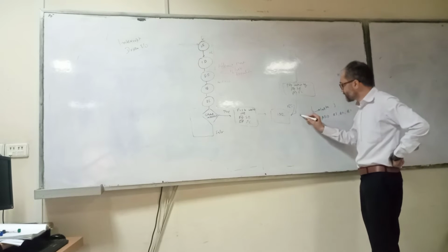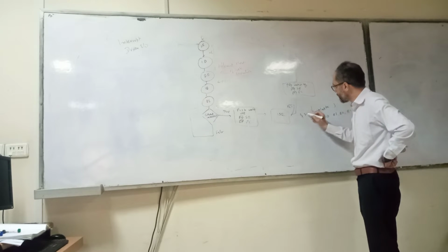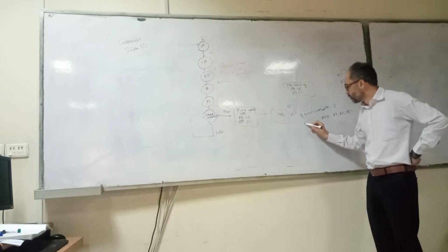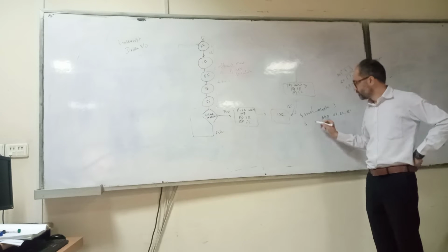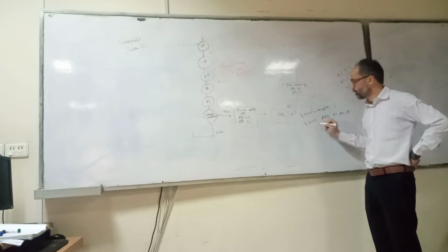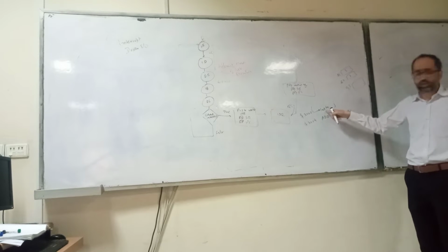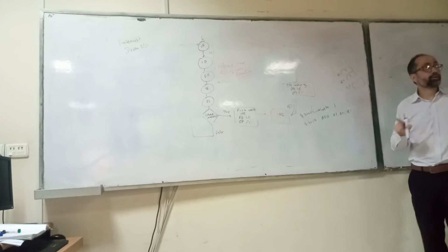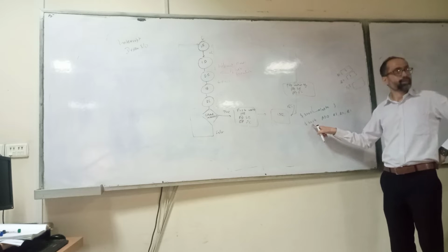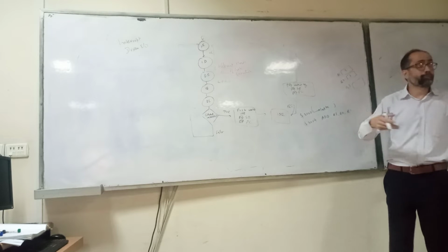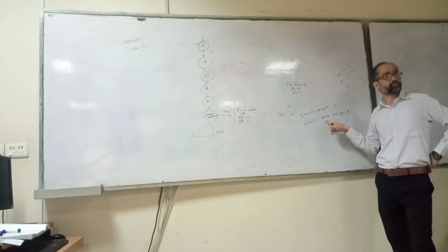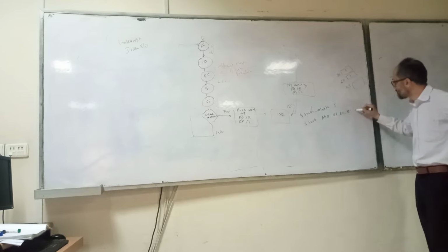Let's assume the address of this instruction is $3000, and the instruction size is 4 bytes. What is the address of the next instruction? 3004. So once we complete instruction J, which value should we store on the stack? 3004. Because when the program is resumed, it will resume execution from which instruction? This instruction, J plus 1.